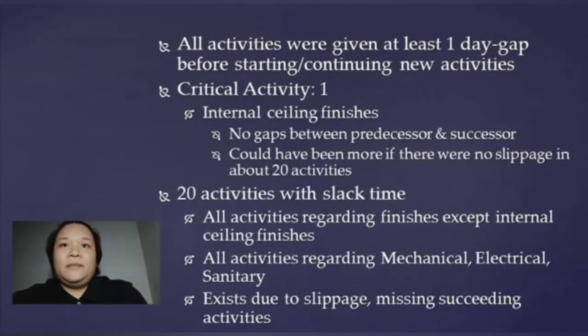For our CPM, all activities were given at least 1 day gap before starting or continuing new activities. We only have one critical activity, which is internal ceiling finishes. There are no gaps between the predecessor and the successor of this activity. It could have been more if there were no slippage in about 20 activities.